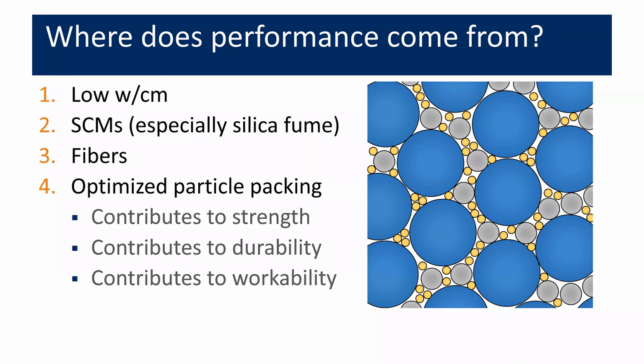When you have that dense packing that comes from having this optimized gradation of particles, not only do you get high strength and high durability, but surprisingly, you also get high workability. And that's because if you look at this figure I'm showing here on the right, when you have a lot of particles together, you don't have as much water that gets trapped in between them. That water is freed up to help lubricate those particles. So you actually see a little bit of benefit with respect to workability or flow properties as well.